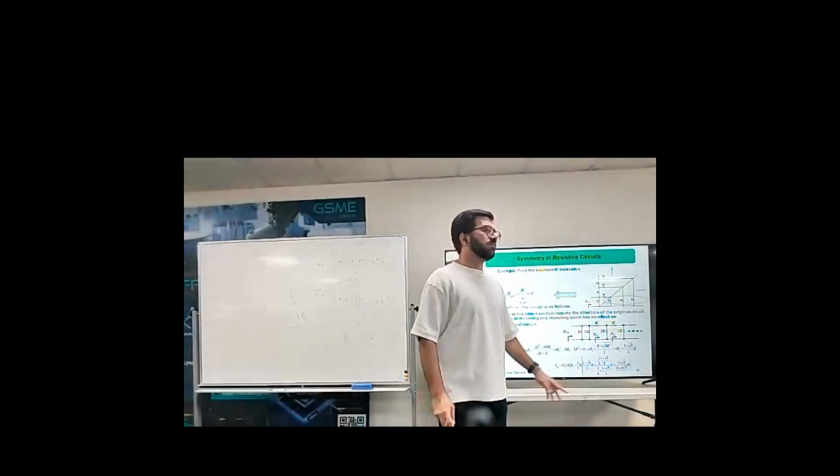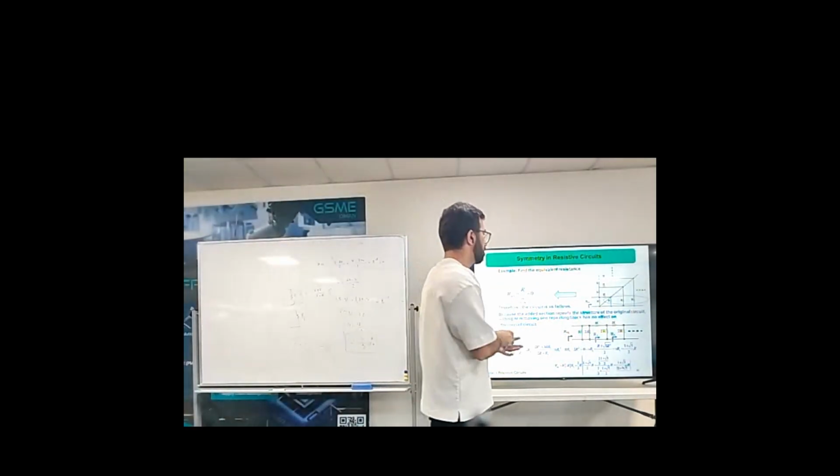If we consider this side as a short circuit, we can write R, we have here 2R. If we draw this circuit, it's like that. And it goes to infinity. Which means the resistor I'm seeing from here should be the same as the resistor I'm seeing here or here. Why? Infinity plus or minus 1 is infinity. Again, it's going to infinity. If you add 1 or reduce 1, it shouldn't affect the result.